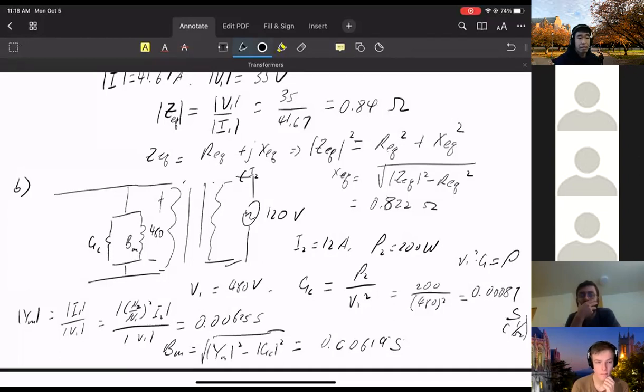For phase measurements, we piggyback on GPS for a synchronous clock, then we measure, and then we know the phase difference. All of these systems in the US now will have at least a few so-called phasor measurement units to do this kind of measurement. It's still fairly expensive.